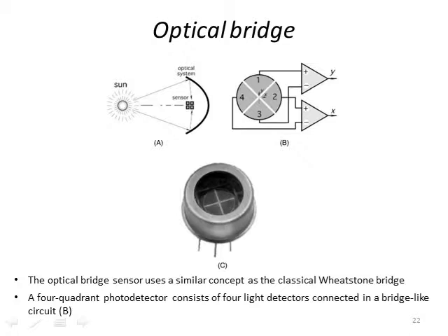As a beam, typically a small beam, is moving, then the amount of intensity that you get between the 4 quadrants is going to change. So you use this bridge configuration between PSD 1, 2, 3, and 4. And depending on not only the XY displacement, but there can be other movements as well, then your XY output of the amplifiers are going to change.